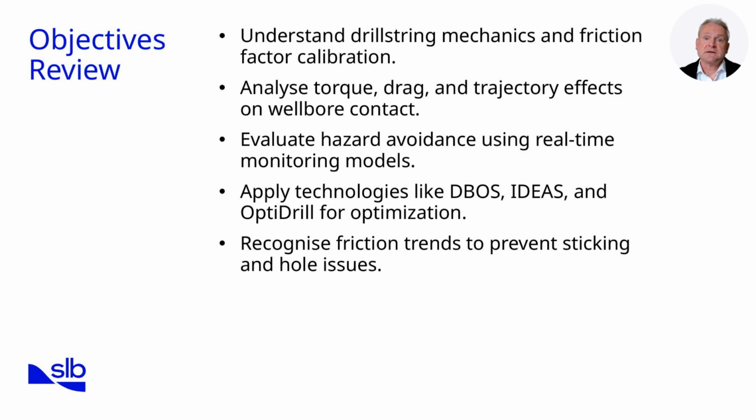The third objective was to evaluate technologies like DBOS, IDEAS, and OptiDrill. We discussed how these systems apply geological data, advanced modelling, and real-time optimization to enhance drilling performance and reduce risk. Finally, we set out to recognize friction factor trends. This was addressed through the exercise interpreting pickup, slack-off, and rotating weights to identify issues such as poor hole cleaning or differential sticking.